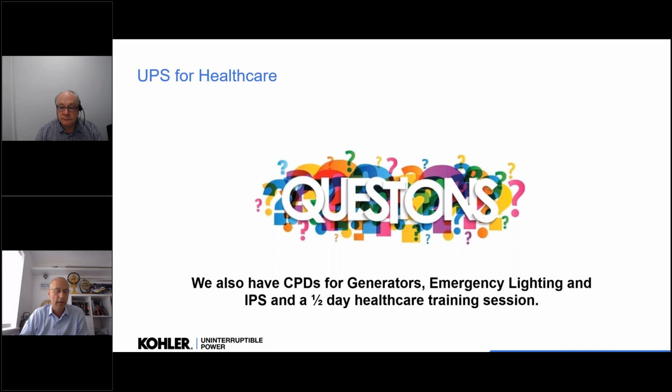If that SPS isn't available, then it's 3 hours. But if you're talking about safety systems as well, there are obviously other regulations for life safety systems that might require longer. But typically for the healthcare HTM guidance, it's 1 hour or 3 hours.